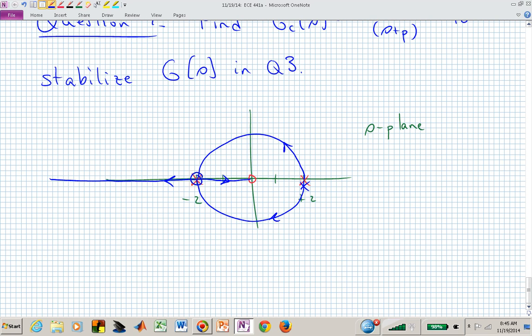Here, in this configuration, now you need to advance that gain k a fair amount. You can't start it close to 0 or you're going to be stuck in the right half plane and be unstable. You have to crank up that gain to be beyond a gain value that would put you here. Does everybody see that? Now you have to be beyond a certain gain value k.